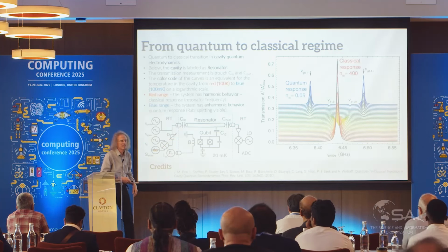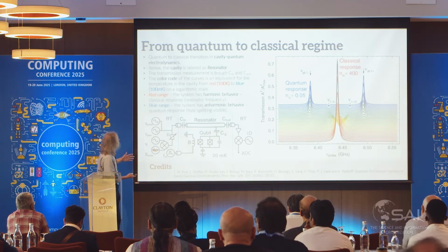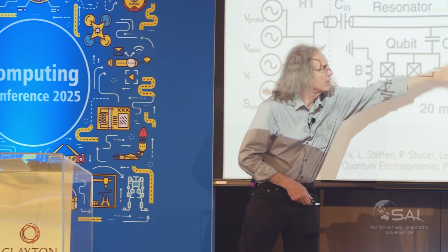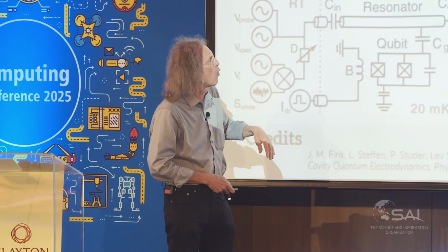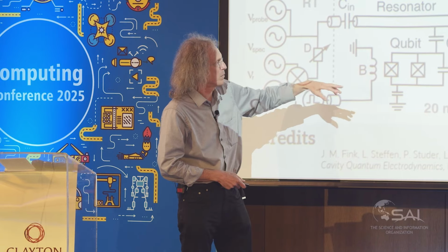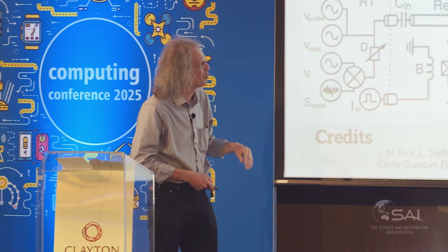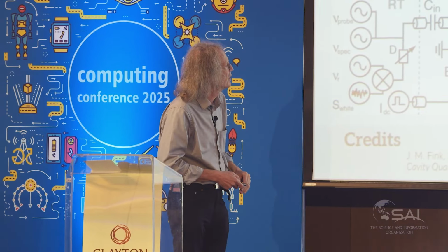In microwave technology, it means just to mix its frequency up on what we have here in the resonator. Now a setup is pretty easy. You have some microwave generators. You feed them here in the resonator, and here you actually homodyne down convert, and you look for your mixed frequencies from the qubit.